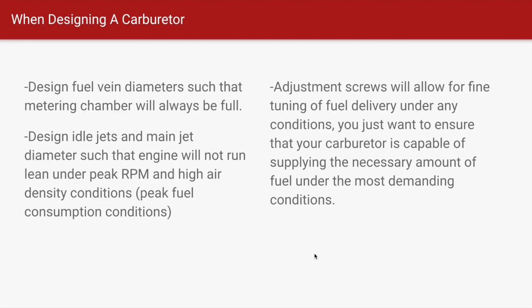When designing a carburetor, design fuel vane, idle jet, and main jet diameters so that your carburetor is capable of supplying the necessary amount of fuel under the most demanding conditions. Although we've not touched on this today, adjustment screws will allow for fine-tuning of fuel delivery under any conditions.